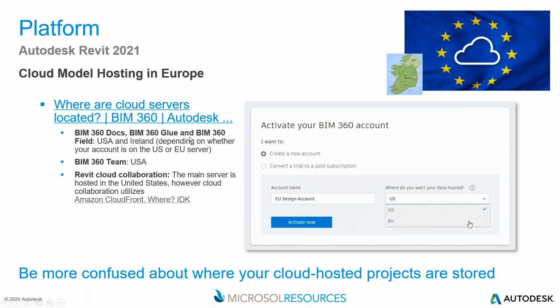But yes, Ireland. When you're creating your BIM 360 account, you can specify where you want it to be, and that's for most of the stuff. It gets a little confusing because there's so many different kinds of data. For instance, if we initiate a model to Docs, it's really using BIM 360 Design. If you're simply saving a Revit model, you can nowadays go File, Save As, and take a cloud model and just host it up to a project. It's not really initiated, not accessible by Revit or by multiple people using Revit, so it's not collaborative. Anyway, there's a lot of options out there, and hopefully this will end up making it more stable and faster.